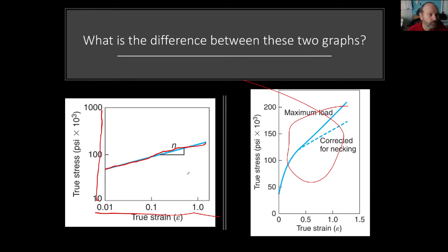And if you put it on a log-linear scale, it would be a straight line. So logarithmic functions are natural, right? Radioactivity is the same way. Cooling, energy diffusion, those kinds of things are all on a logarithmic scale. So are lots of material properties. So if we plot true stress versus true strain on a log scale, we get a straight line.